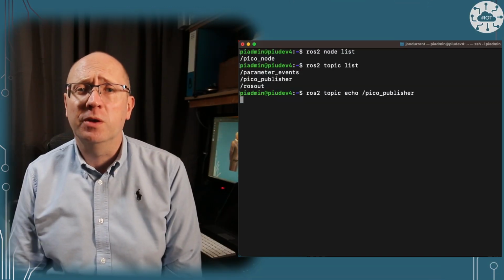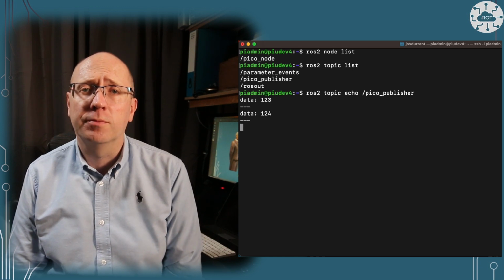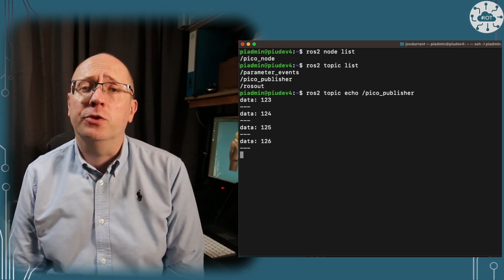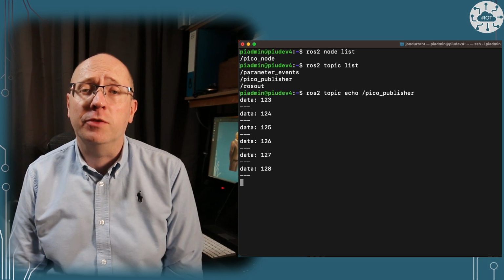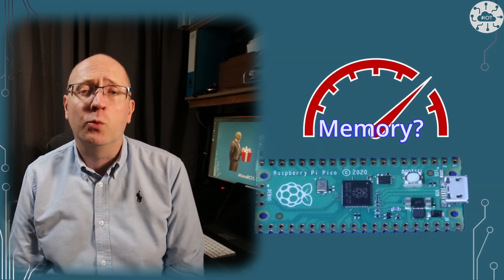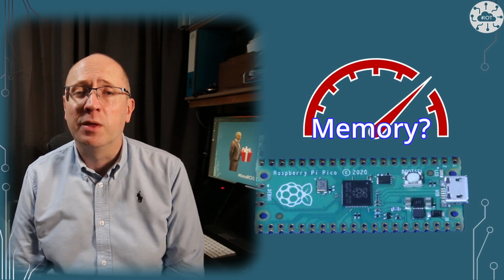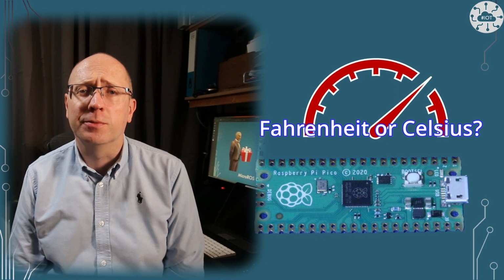In a previous video, I showed the Micro ROS demo on Pico, building a ROS2 ecosystem and connecting our Pico to it. The Pico didn't do very much, just published a counting message. When working with ROS2, it's recommended to use specific message types. So if we want to publish the temperature of our Pico, we should use a temperature message type and not just use any message type that happens to include a float.